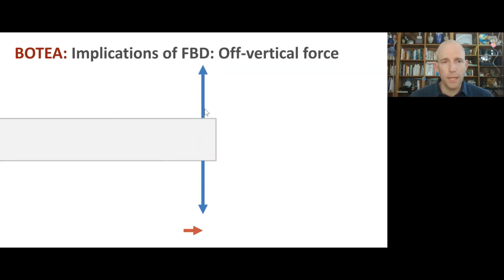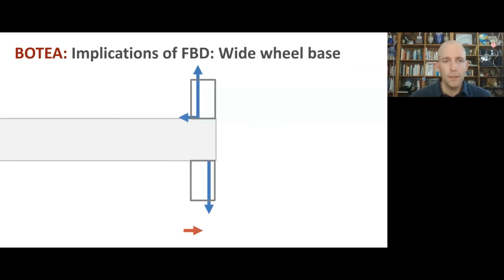With these forces not being offset at all side to side, in order for us to achieve static equilibrium just from these forces, we would need them to become infinite, so that an infinitesimally small side-to-side offset would lead to a finite moment to overcome this moment. And that's bad, right? That's going to put big forces on our structure.